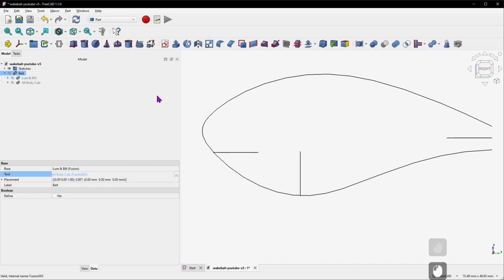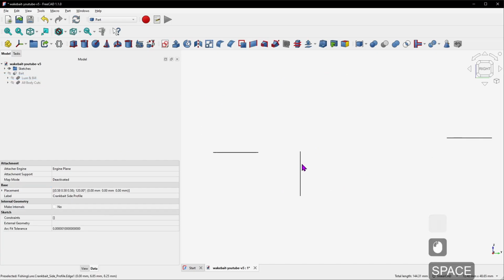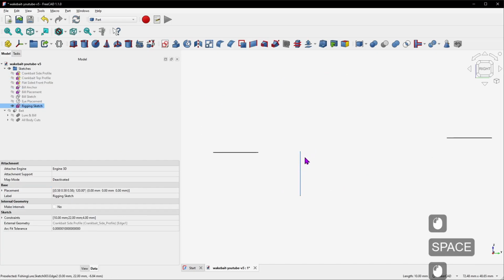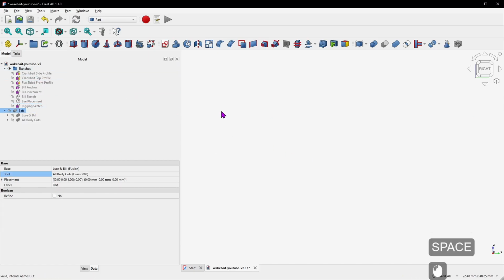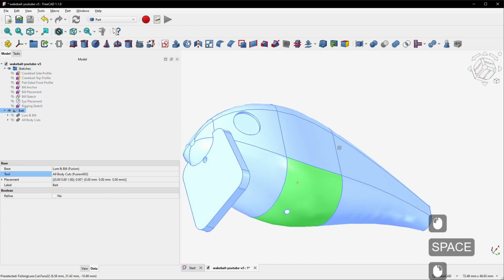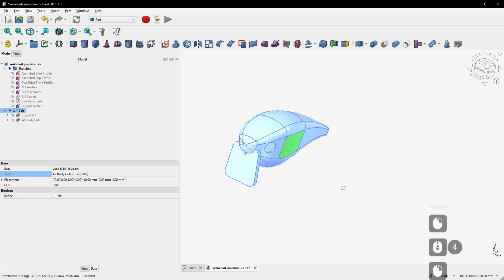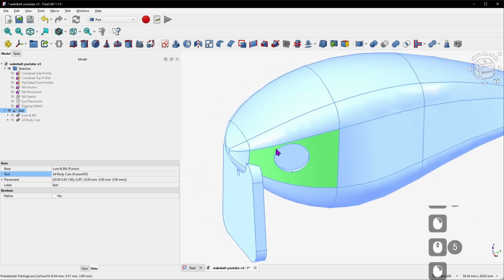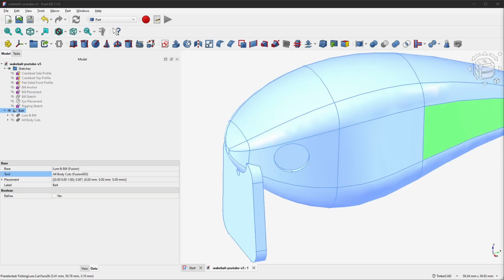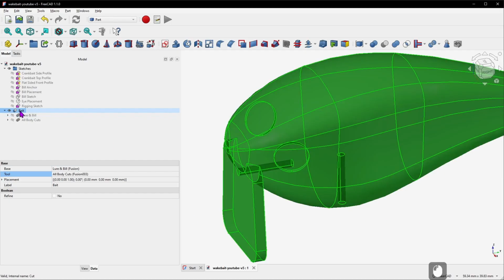And when we do that and hide these sketches, I'm just clicking on them here and then hitting the space bar. I bring the bait back, you're going to see that the pilot holes are there along with the eyes. And the only thing we have left to do is to create our rattle chamber. To make the weight chamber, we will create another curved array inside the body and cut it out. So let's go ahead and hide the bait for now.